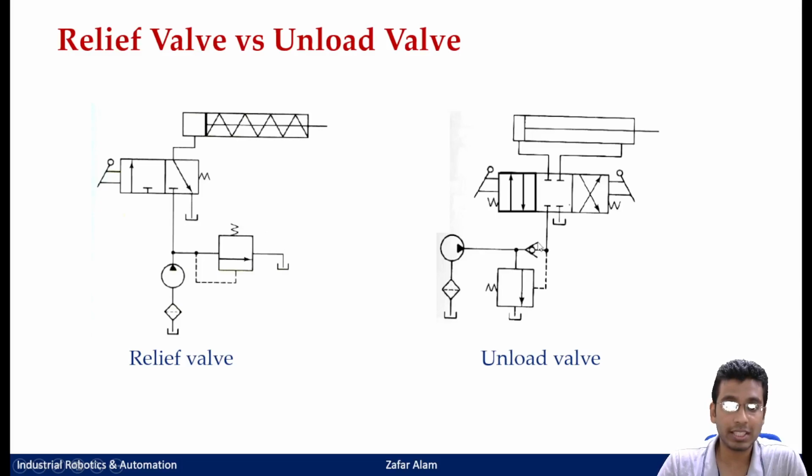Now see, in this case, since there is a check valve in between, if you see the left figure here, we are putting one check valve here, and after that check valve we are putting this dotted line, that is the pressurized line. That means your 150 bar pressure cannot go this side. That 150 bar pressure would remain in this line, and that is also holding your spool towards the center position.